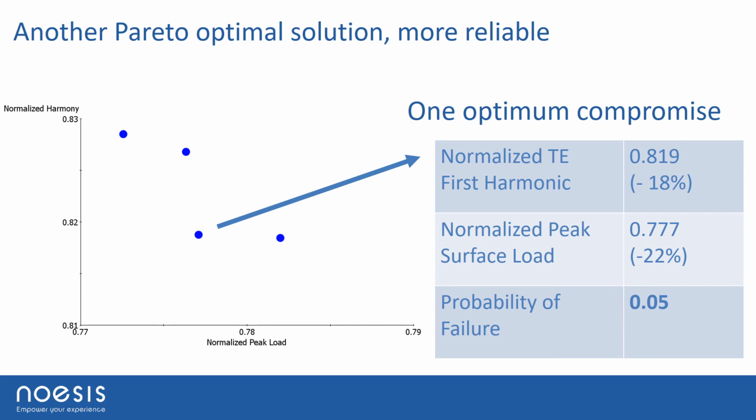And if you add some probability to have some wrong value during the design with a certain probability, which is about 0.4 micrometer for all of those inputs in terms of sigma, we get the probability of failure. So the failure means one of the constraints will be above 85%. So the probability of failure will be less than 5%. So that's usually what we call a 3 sigma analysis. And so now we have another solution which is more reliable. It's not as good as the one we had before, but at least we know that small changes in our inputs are not going to have a dramatic effect on our outputs.